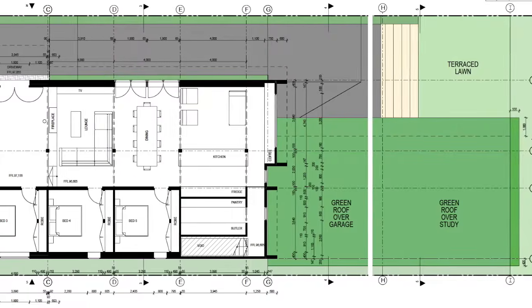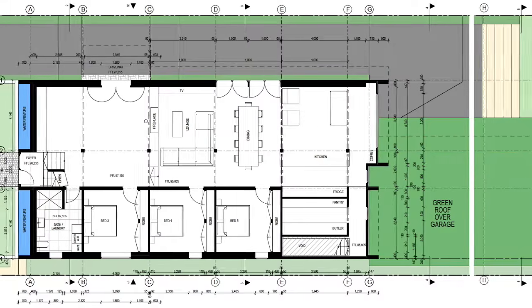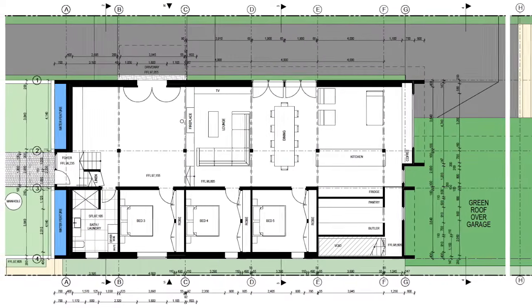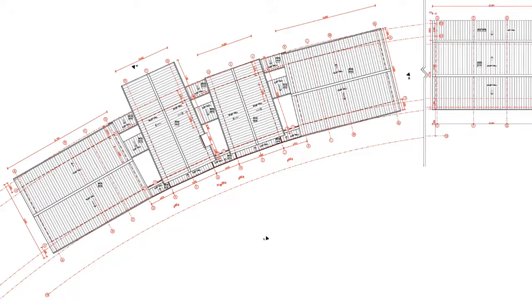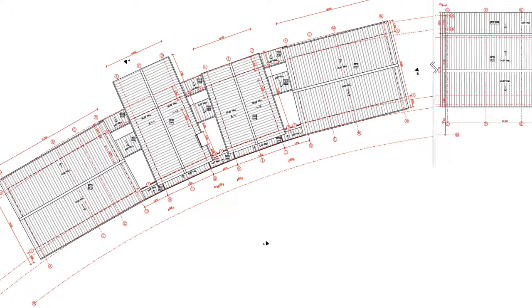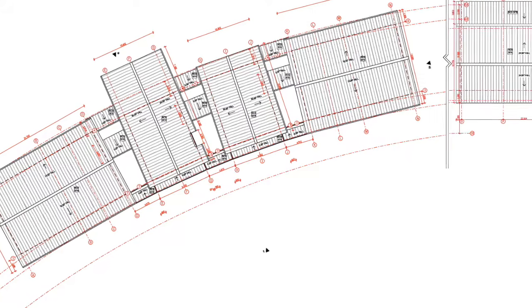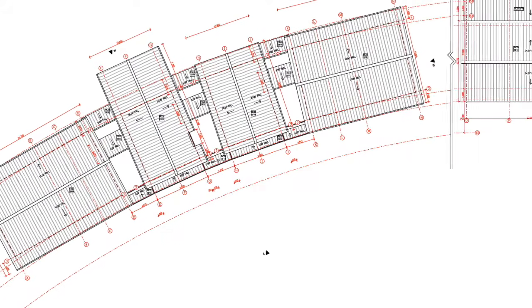Once we're through the site drawings, we may then be looking at the floor plans. So a floor plan is a horizontal sectional cut through the building, taken at each story, if it's a multi-story building, explaining what the inside of the house looks like. A roof plan is where we're viewing the building from on top, like a bird's eye view, seeing what the roof would look like, what's the shape of the building, what's the materiality of the roof, is there skylights, and we generally will also be showing a dashed outline of the exterior envelope of the building below, or the outside of the walls, to explain the relationship between the roof and the walls.